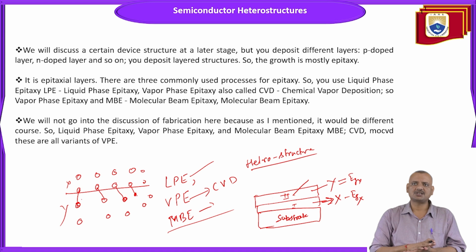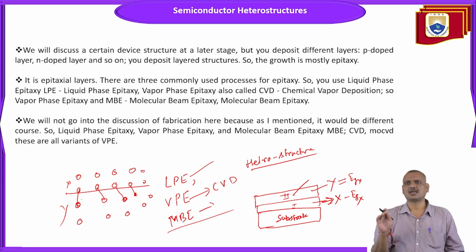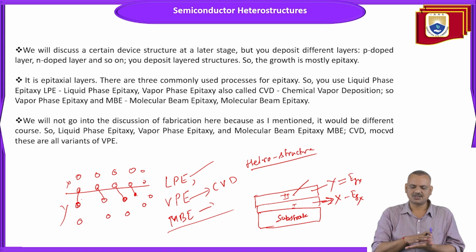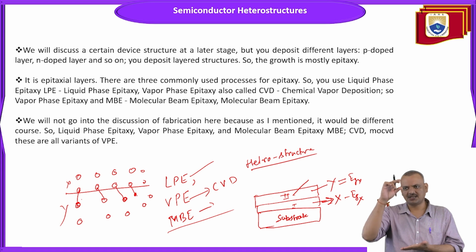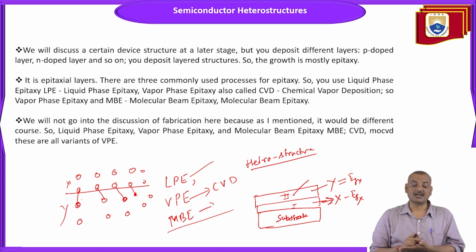So heterostructure matched layer and heterostructure mismatched layer: there are two concepts. So a matched layer is okay. Once the heterostructure is a matched layer, there will be no non-radiative state in between the conduction band and valence band. Why?